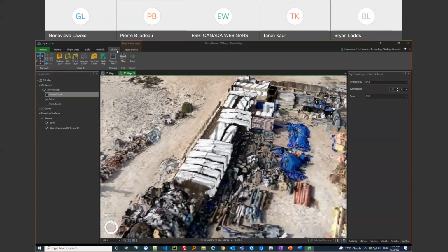If you would like to share the scene layer package, you would do so through your scene layer. You can share your orthomosaic through a tile layer, and your DSM and DTM through an elevation layer, and obviously you can use a web map to share your web content. Soon we will be able to use the imagery layer for your orthomosaic. That's upcoming. It's on the roadmap for ArcGIS Online. And of course, you would have to be linked to your ArcGIS Online account or through a portal.